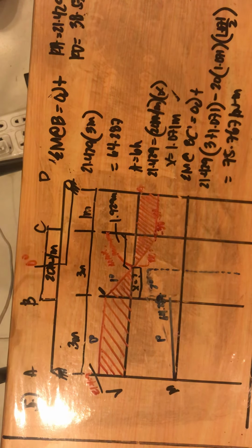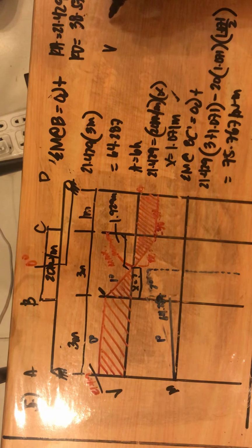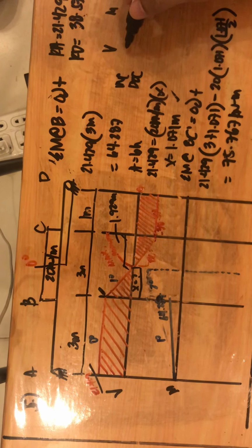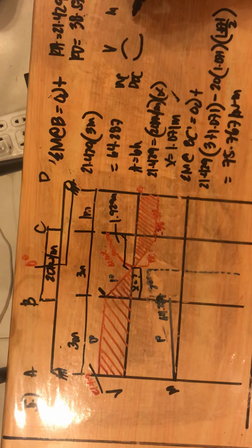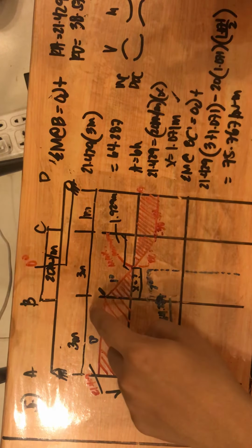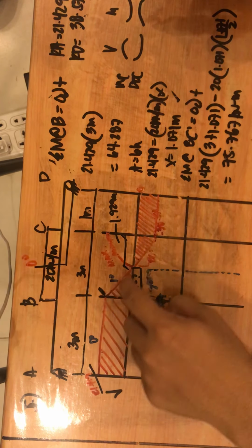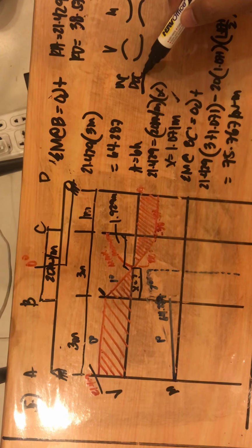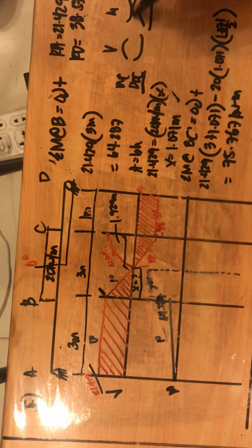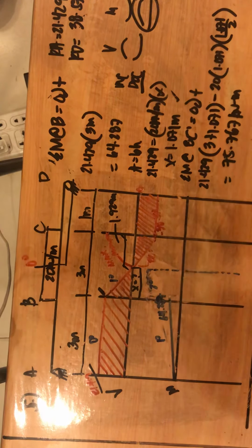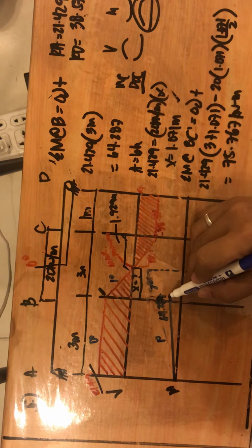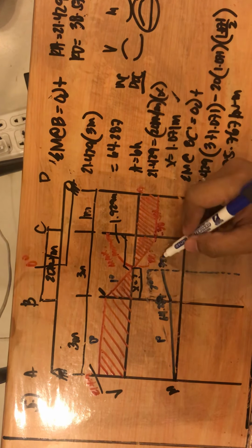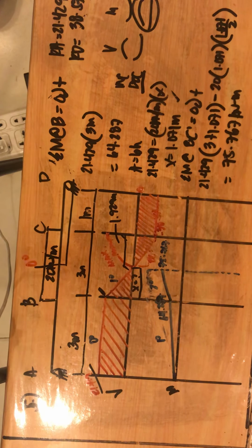So how does our graph go again? For shear, then moment: increasing, then decreasing. This is sad, happy, sad. Based on our graph, from point B up to the maximum moment location, our value decreased. Since we are drawing the moment, we use the sad curve. So from point B up to the maximum moment, our graph is sad, and its value is 75.767 kilonewton meter.